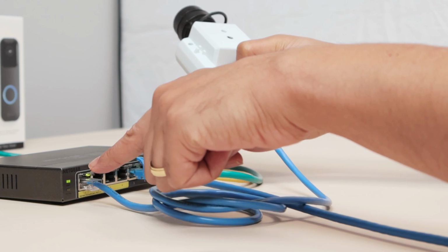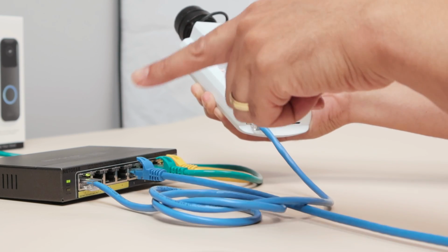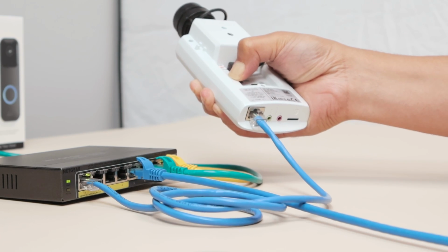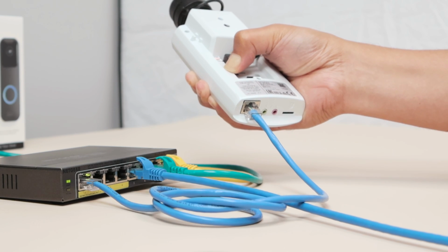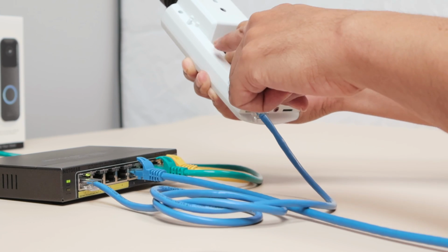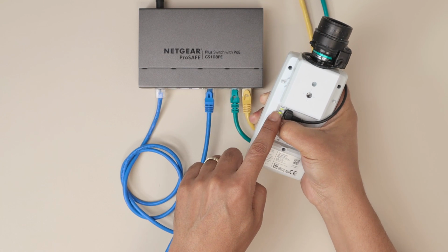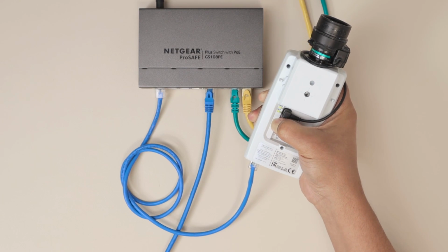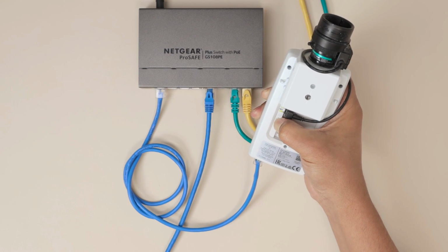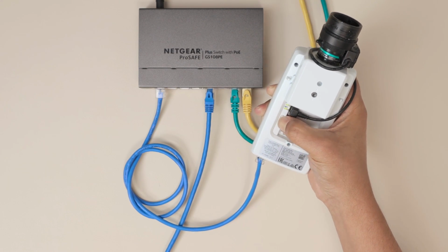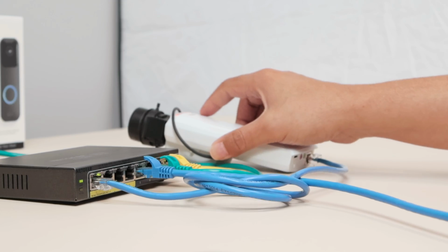Here I have the cable with the PoE power, so the cable is powering the camera via power over Ethernet. So it's an IP camera with power over Ethernet, works that way. I'm just holding the button here. It changes to green now. The LED, as you can see, was in a different color, was amber, and then changed to green. And I will release because I think it's time to go. So just release the button here, put the camera back into its place.